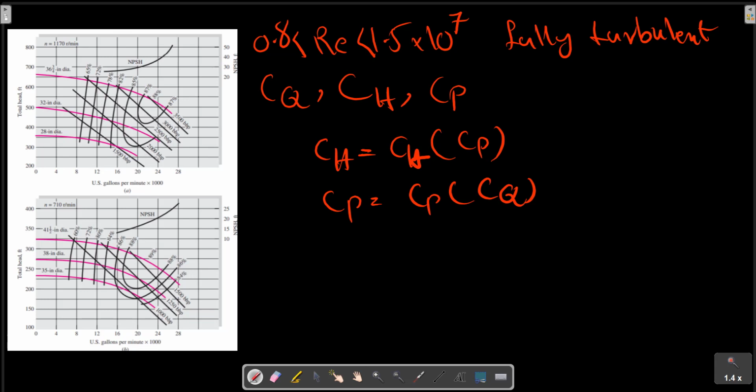Large pumps have smaller ratios of roughness and clearance to impeller diameter than small pumps. In addition, a more viscous liquid will have significant Reynolds number effects. For example, a factor of 3 or more viscosity increase causes a clearly visible effect on CH and CP.